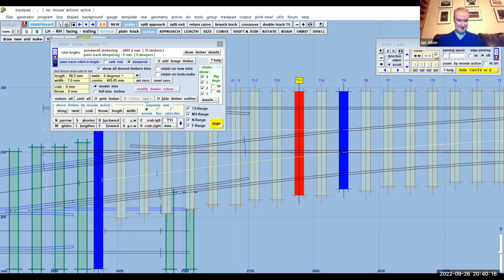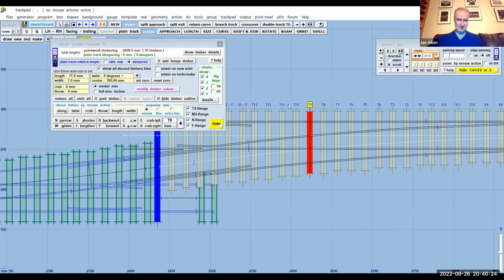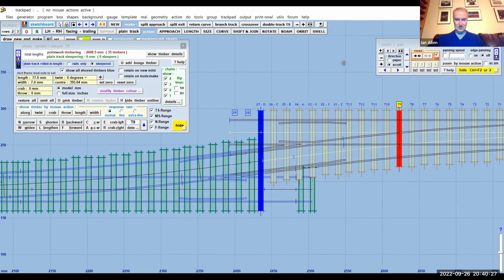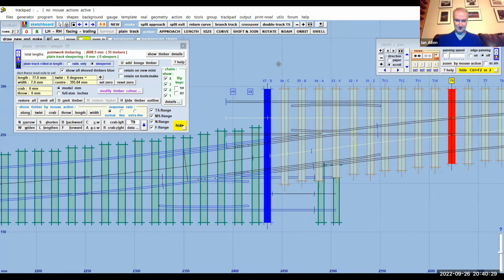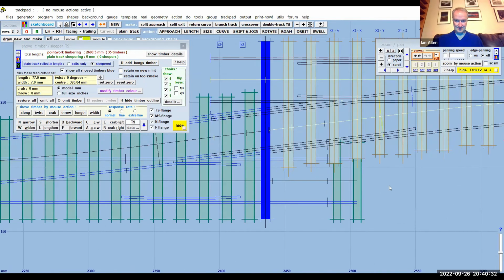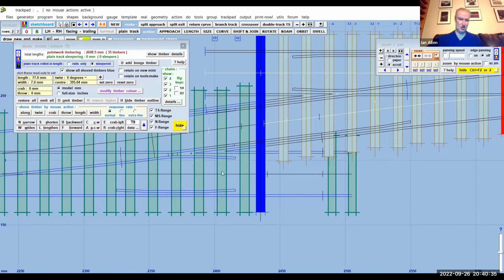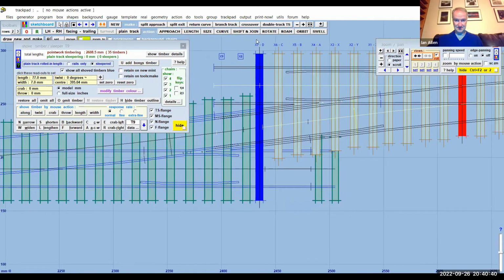But where you've got a long timber running across double track like you had there, the standard length is 19 foot 6 inches, and there isn't a longer length available from the timber yard other than by special order. And then what they would do is they'd join them in the middle, wouldn't they? So I wanted a longer one, but there's no harm in just leaving it a fraction shorter. So let's just restore that one then. You need to select it, and I'm going to lengthen again. If you look on the length now, it should be 19 foot 6.